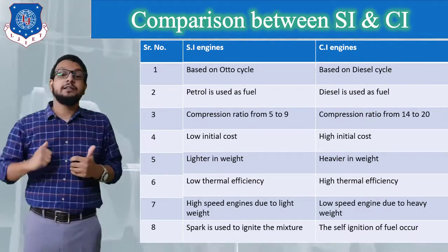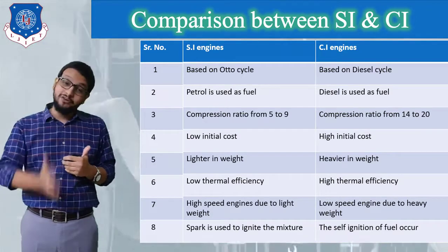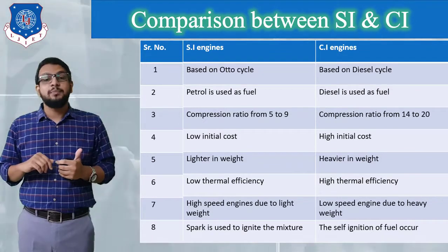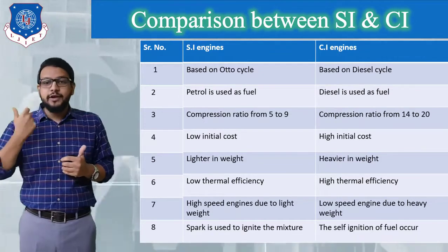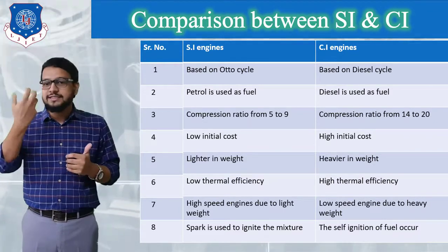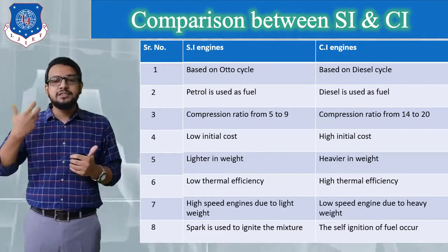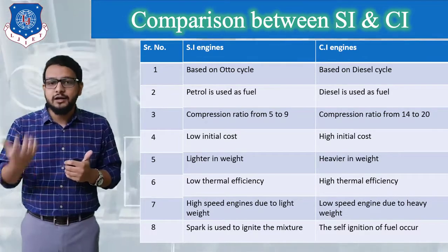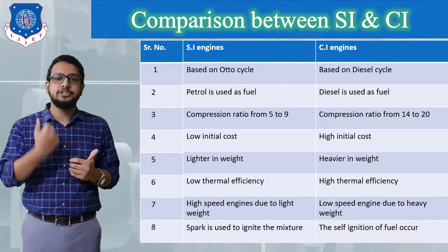So we can say there is a low initial investment in the case of the petrol engine, whereas there is a high initial cost in the case of the diesel engine. Now taking the case of weight, which engine will be heavier? It is very obvious: since the thickness of the cylinder and piston are increased, the diesel engine will be heavier in weight compared to the petrol engine.